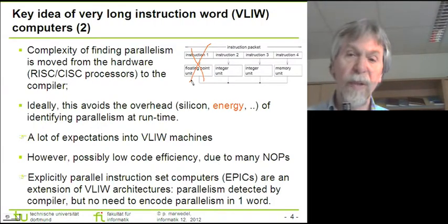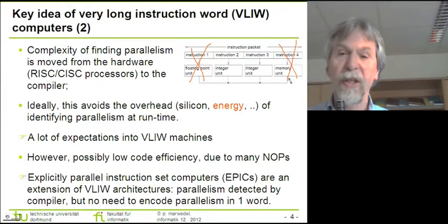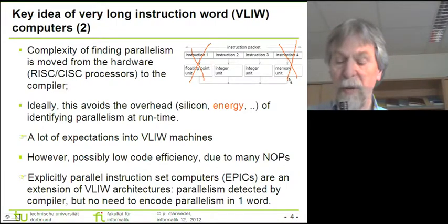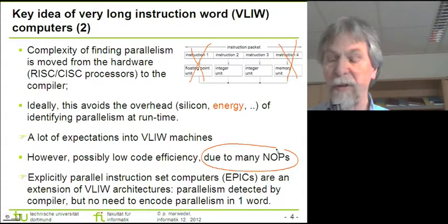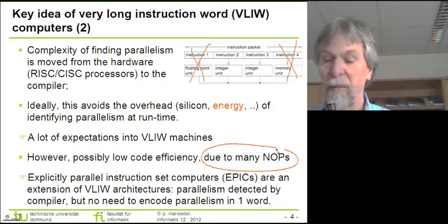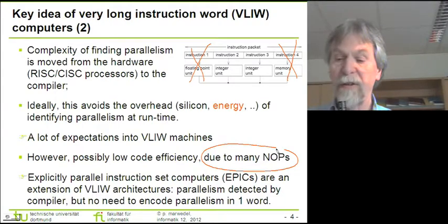It could also happen that we have quite a number of registers and all the variables can be associated with registers, and that therefore we don't need any access to a memory, so we can also not take advantage of that slot which is there at the right hand side of this little figure. As a result, we might have to place quite a number of no operation instructions into these slots, and this of course means that the instruction density, the efficiency of the instruction code, is decreased.